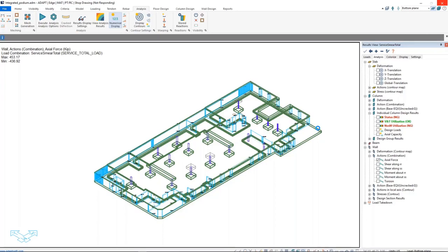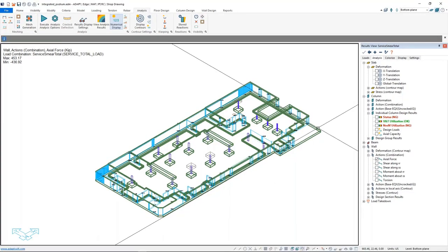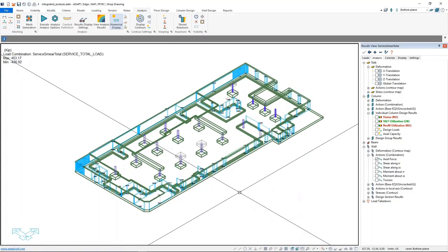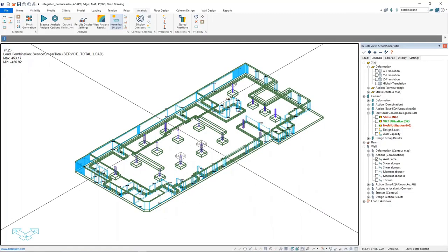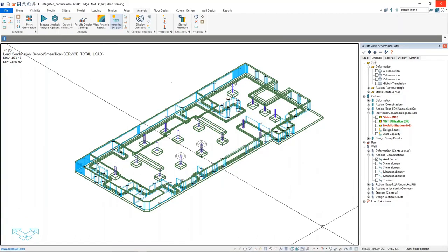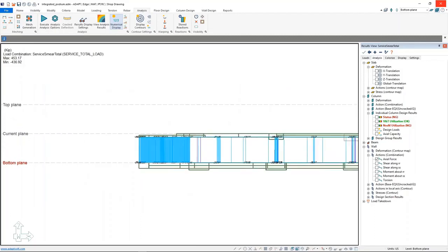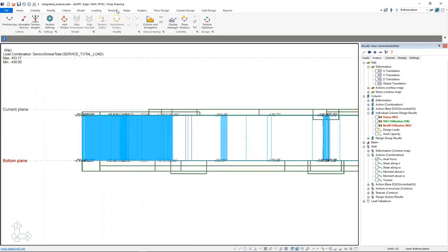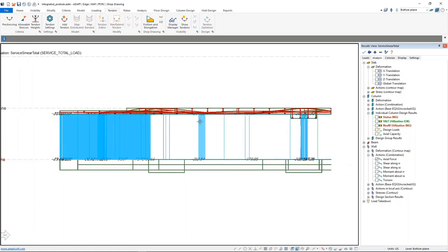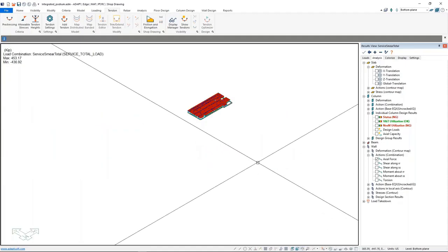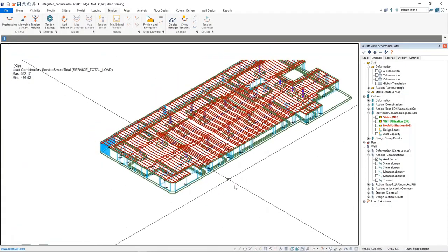I realize whenever I'm on these webinars, my computer runs a little bit slower. So now we're actually in the full mode. You see on the top right, I have my multi-level mode. If we look at this from the side, you can now see the full concrete podium that we're modeling. And if I turn on my tendons, these are the tendons that I would have had in my podium. And then we're transferring those loads based on the process that I described down to the foundation.